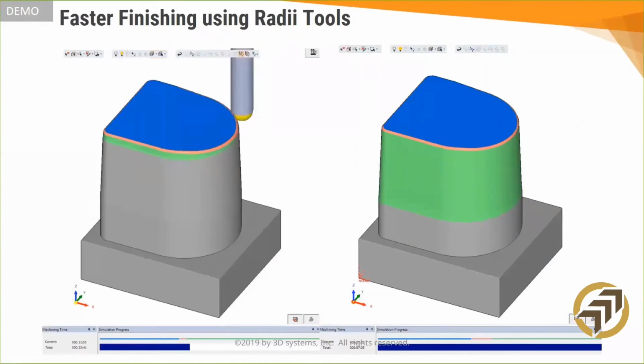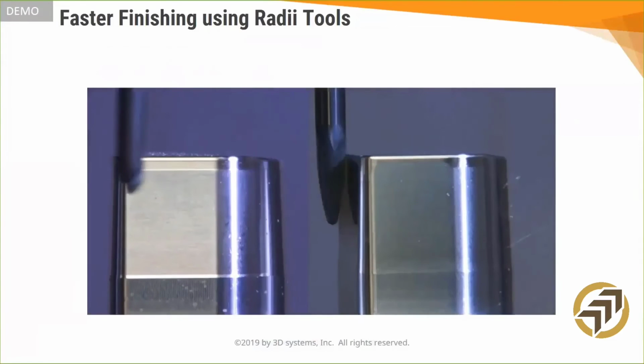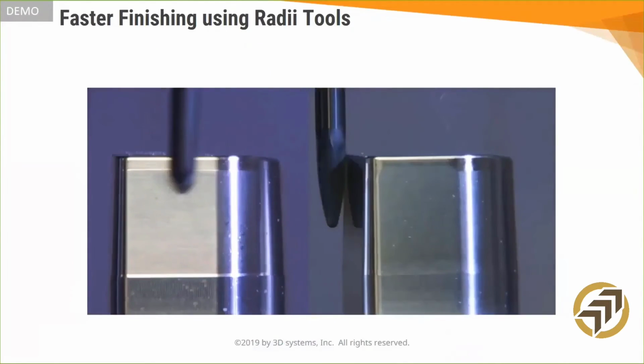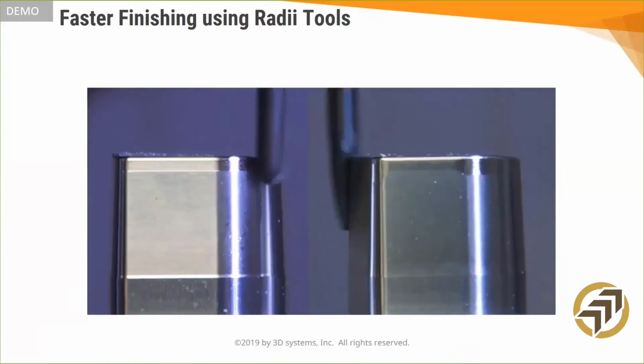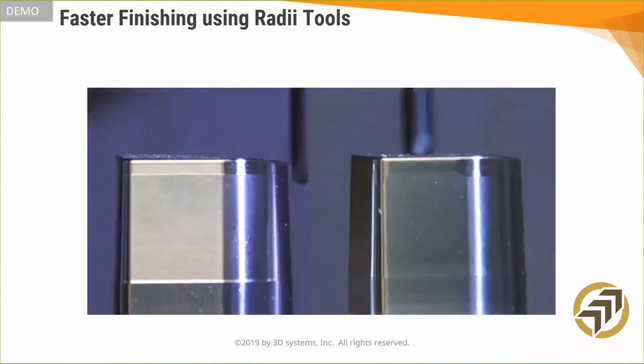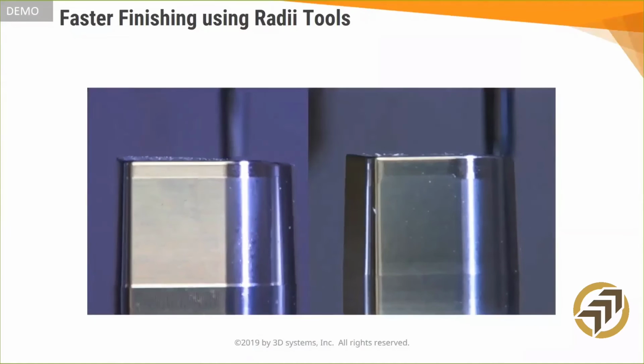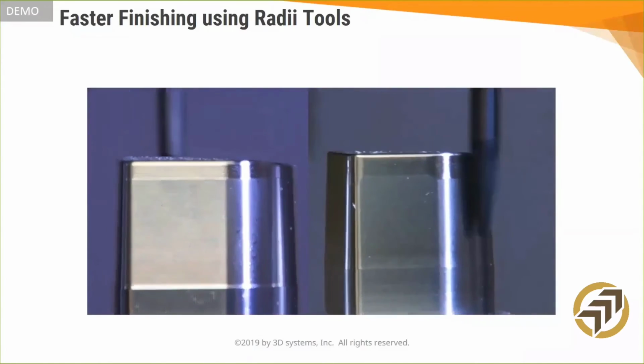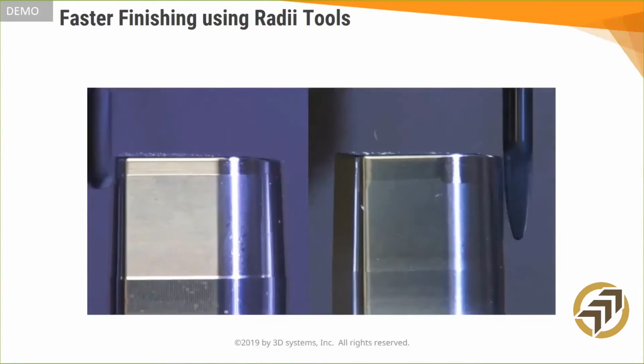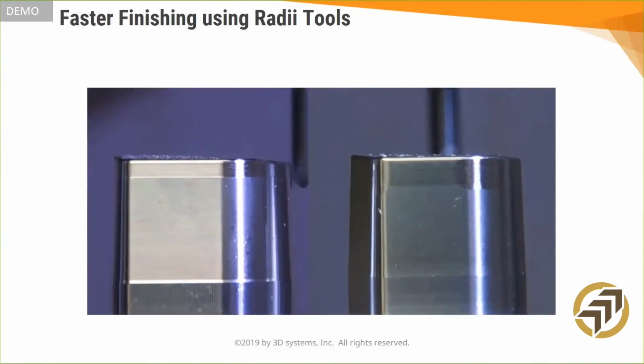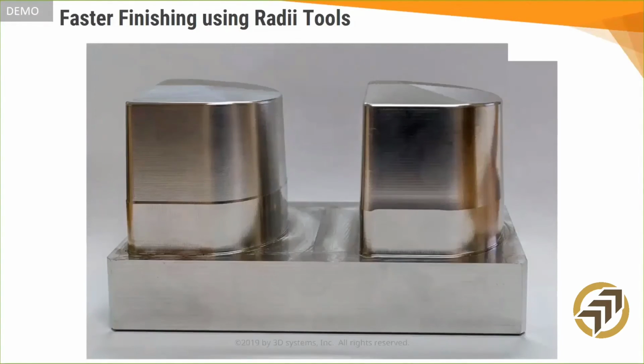When compared to machining with a standard ball tool, a combination of lens and then oval cutter on this mold insert cuts finishing time by more than half. It's due, of course, to utilizing the larger curvature radius of the cutter in its optimal geometric zone. A lot of the machining that mold parts require is a good fit for these special cutters. And while they're currently more expensive than regular ball cutters, it's a great way to cut time on the CNC machine. Having the ability to utilize these new cutter shapes is an important feature for your NC software.